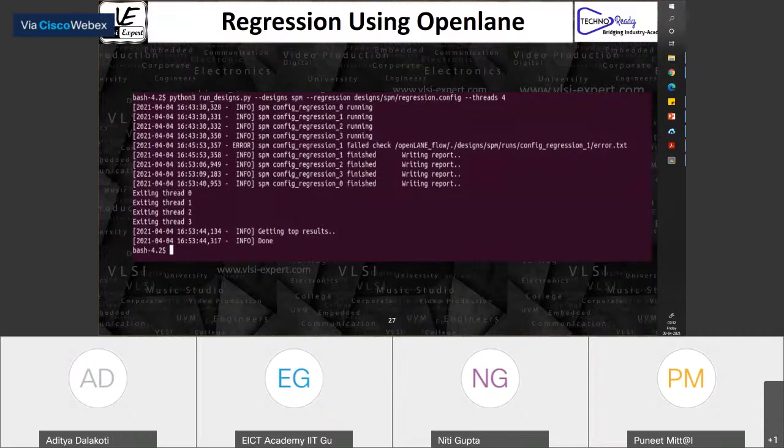On frequency analysis, explore. Frequency analysis and limitations are actually done from custom. A lot of clock tree estimations are first done using custom simulations in SPICE, then noise estimations in SPICE, and then how those reflect in actual clock trees. Clock tree synthesis and design and clock frequency analysis is itself another whole research area, basically.